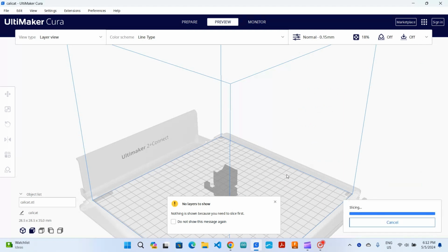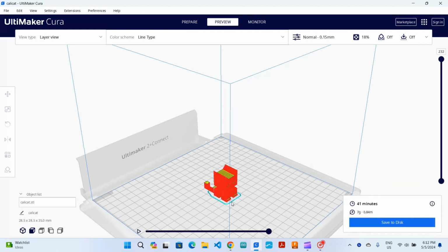And then you can see what that looks like. Basically, it just goes a lap about a couple millimeters away from the base of the print. And that way, as well as the prime blob, you've extruded some filament, and you now don't have to rip that extra piece off of your print. So it just saves you some post-processing time.